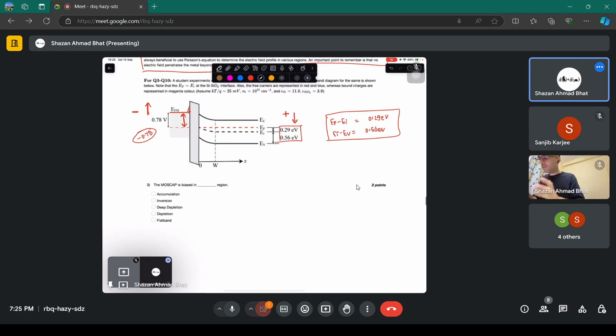Now, going to the basics. This is an N-type. How do we know it? Because the Fermi level is close to the conduction band. And you have to look outside the depletion region always whenever you look at the Fermi level in the MOS. You have to look at this particular Fermi level here, not in this region directly.